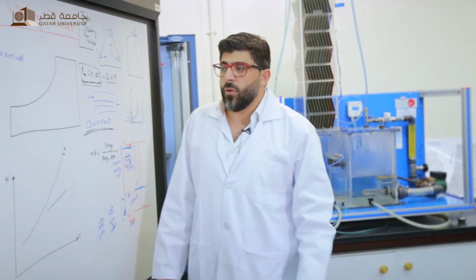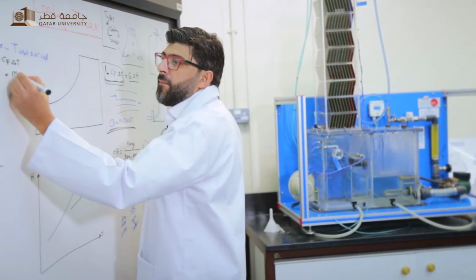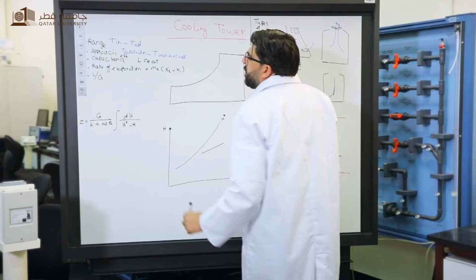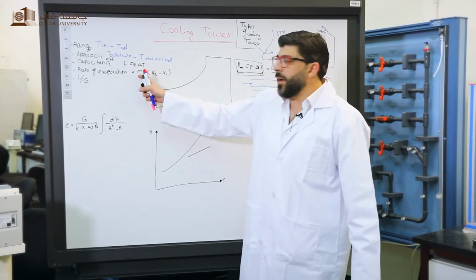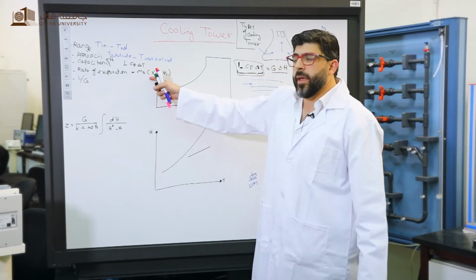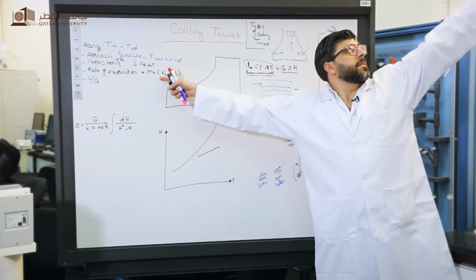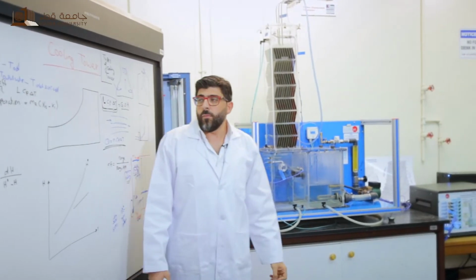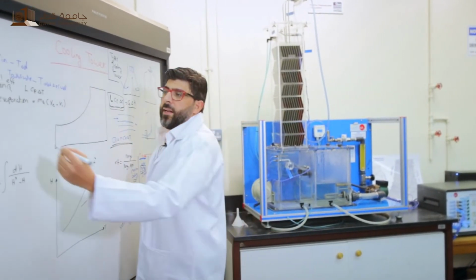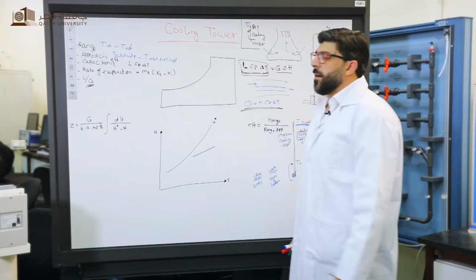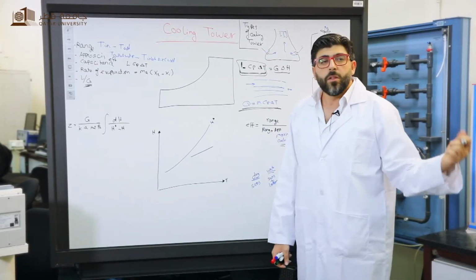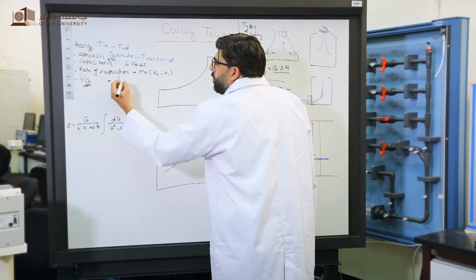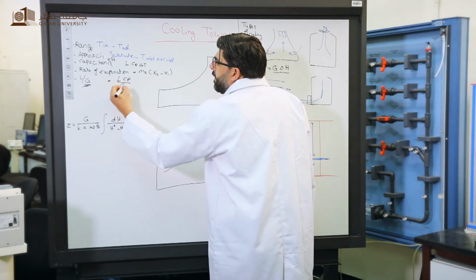So we can determine the rate of evaporation from Ma times (x2 minus x1), where Ma is the mass flow rate of dry air, x2 is the humidity at the top of the column, and x1 is the humidity at the bottom of the column. Also L/G is the flux of liquid to the flux of gas, so L/G is also equal to Cp... L Cp over G.